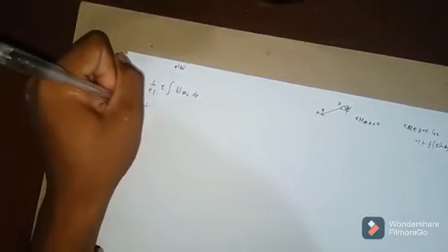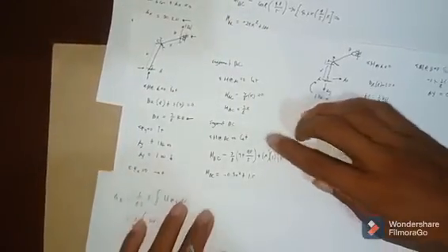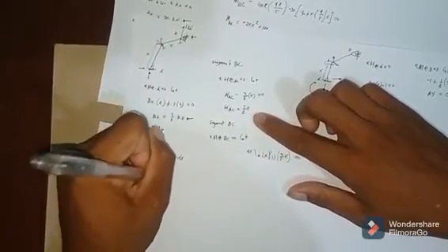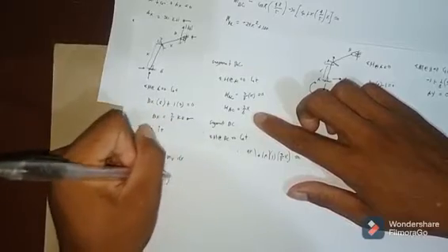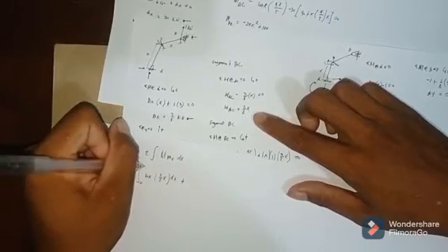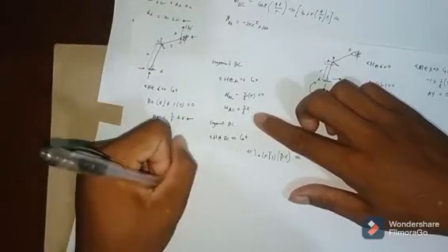So it is equal to 1 over EI integral of 30x, the first thing is our virtual, times segment BC, which is 3x over 8 times 3 over 8x dx plus, and the limits is 0 to 4, and then integral of 0 to 5.